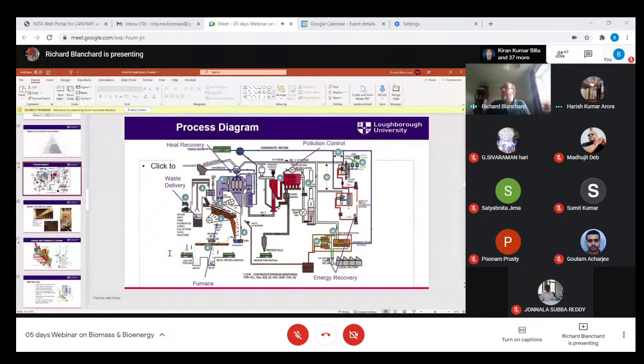Right, so this is a typical waste to energy plant. Can you see that okay? Yeah. Okay, so this is the boiler system in the middle here, the economizer. We then go through adding lime and carbon here, so that's for the acidity and also for the carbon. And then that goes into filters. So this is our filter process, and then that goes up to the flue gas. So that's our main route.